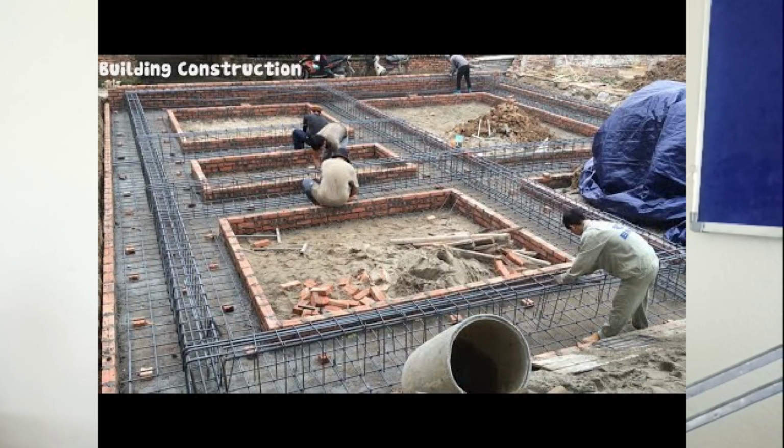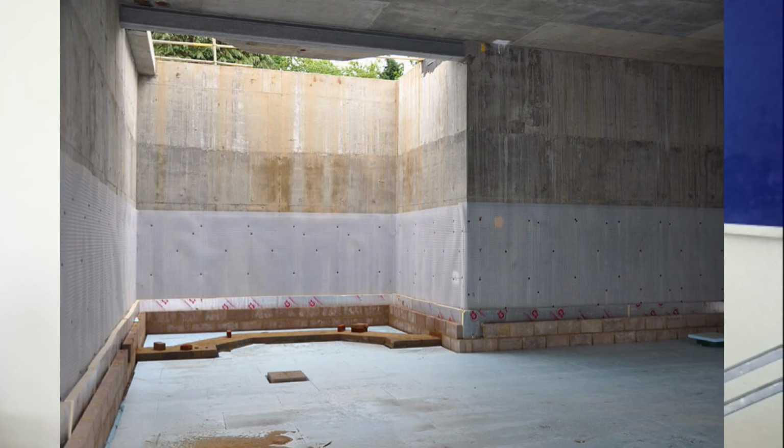After the foundation beam, with the same process you need to have the foundation floor also. Foundation floor means, for the basement you need to have a floor, right? That floor is connected with all the beams, similar to a slab, and you need to provide the steel reinforcement for the basement floor. So that RCC floor, which has steel and all those things, you need to do.